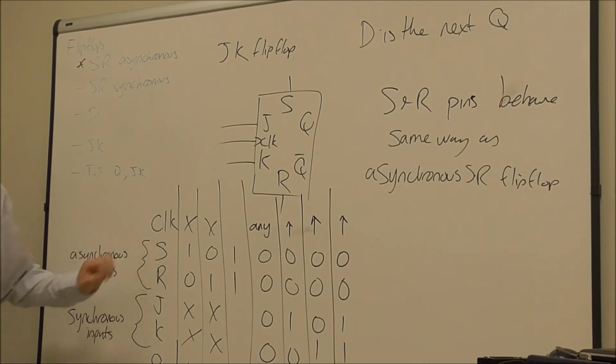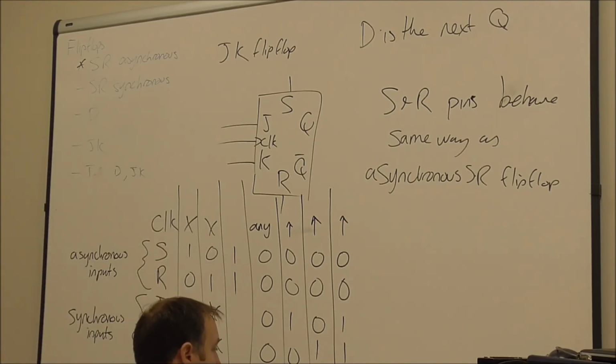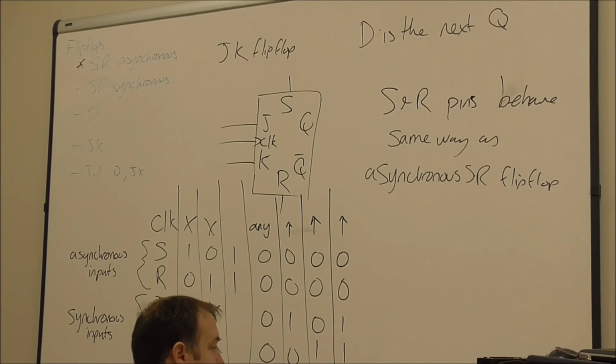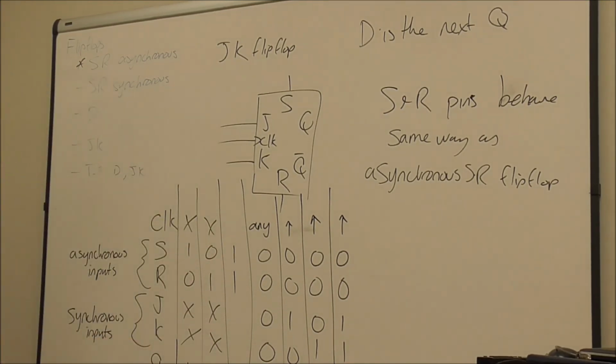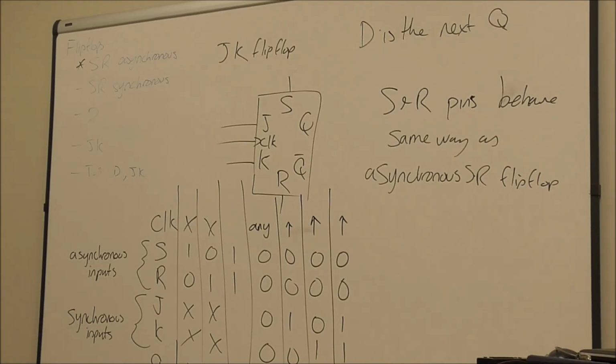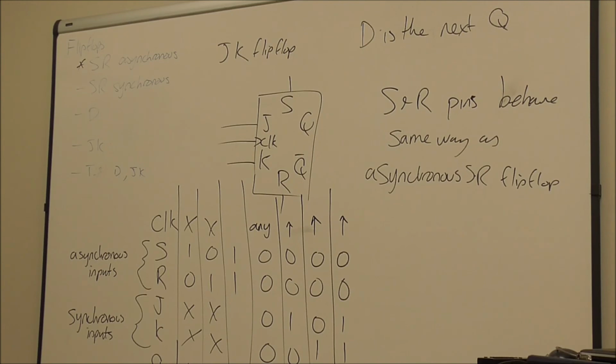The JK flip-flop is wired slightly differently. What it does is it sets it to toggle mode. So if Q was 1 already, and J and K are both set to 1 and it sees the clock edge, it'll change it to be whatever it wasn't before, so it'll make it toggle.